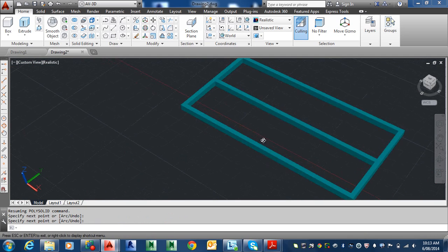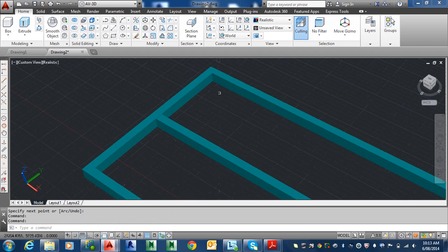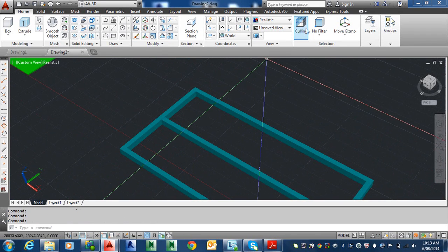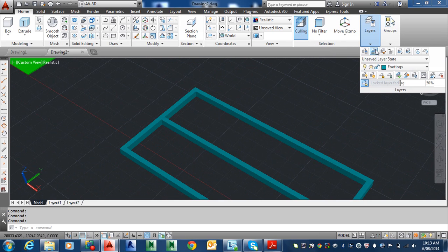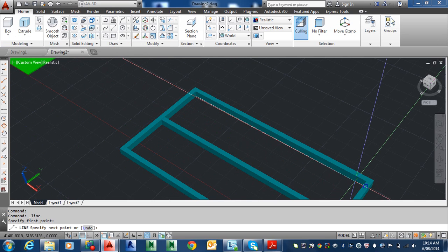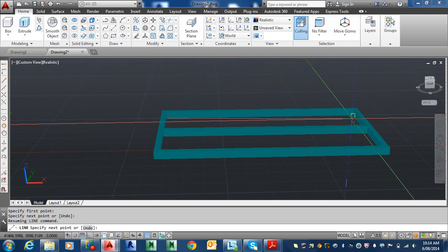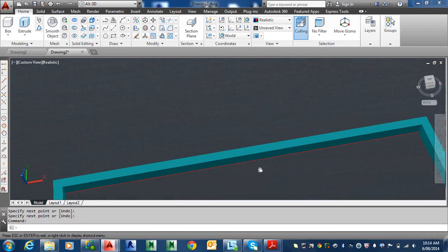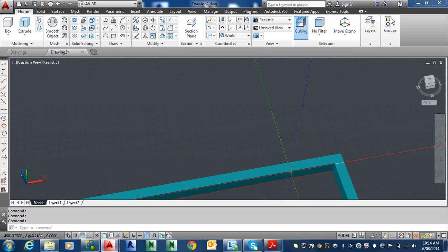That sets it. Now, how are we going to do this one here? What I propose we do is draw a line down the bottom of this here. If I find the layer, we'll go down to the sketch, and I draw a line, alpha line, or you can click the line command from here. Just draw from here to down the bottom there. Okay, so I'm going to use that line as a construction line. Just zoom in, looks alright.